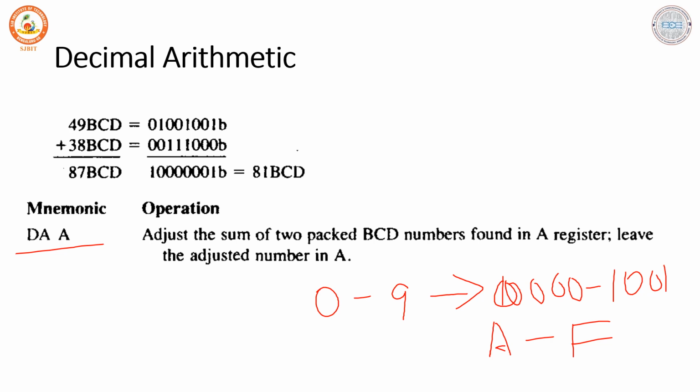This particular addition would set the carry flag, because 1001 is 9 and the next number has to be a higher value, so that has to be taken and stored in the carry flag. If the carry out propagated all the way through the 8 bits, in that situation I'm going to set the carry flag. If the carry flag is now set, or if the higher order bits exceed 9, the higher order bits are decimal adjusted by again adding 6, to produce a proper packed BCD, ranging from 0 to 9.